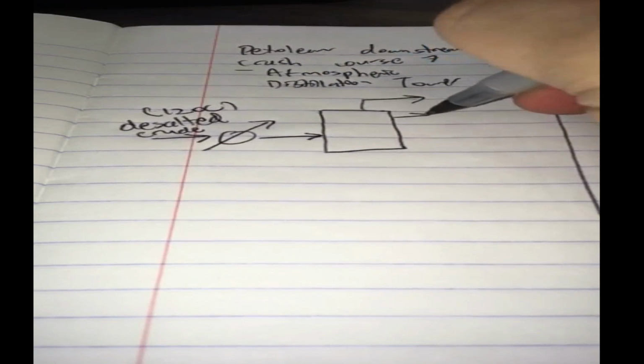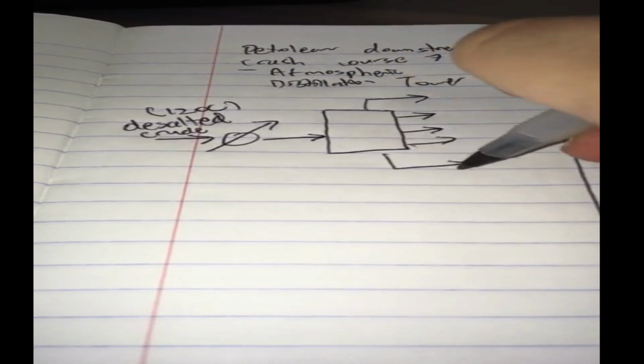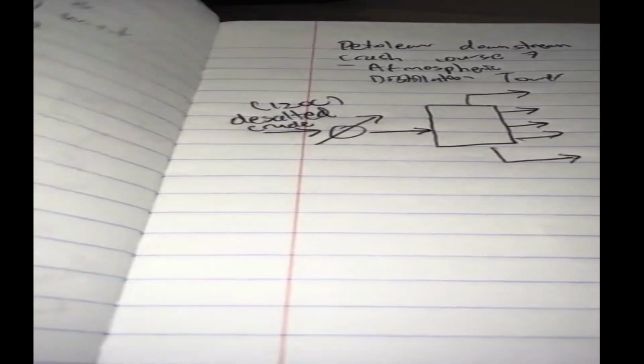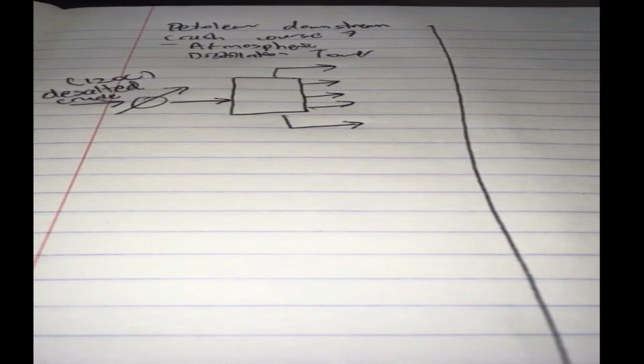And as we all know, we all see this big column, as famously shown in many videos, what this distillation tower would look like. Something like that. But how do we arrive at the design of an atmospheric tower or atmospheric distillation column? So, what do we remember about distillation before? We have ASTM D2892. This is a standard distillation test with 15 plates and a reflux ratio of 5.